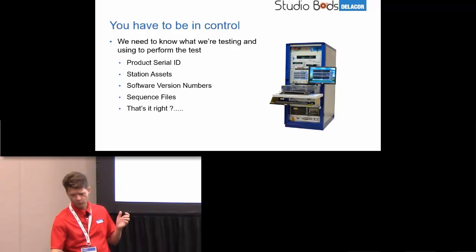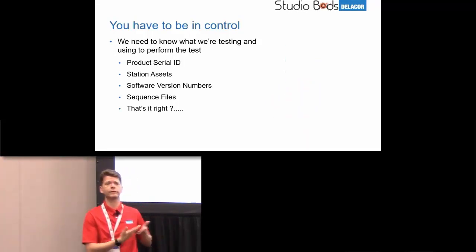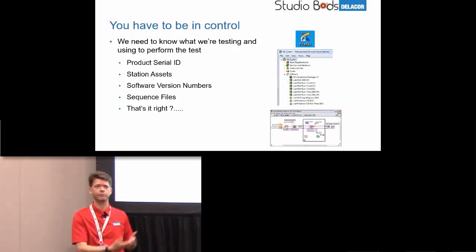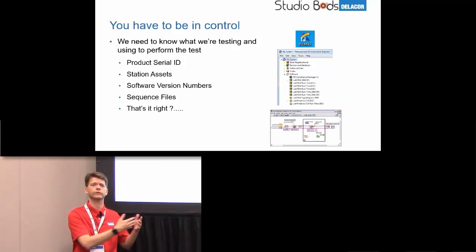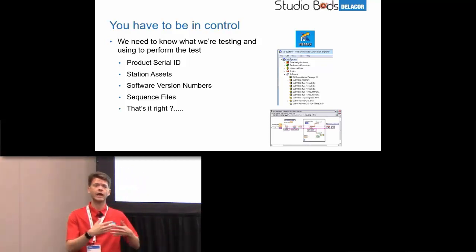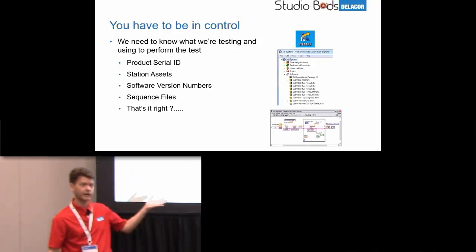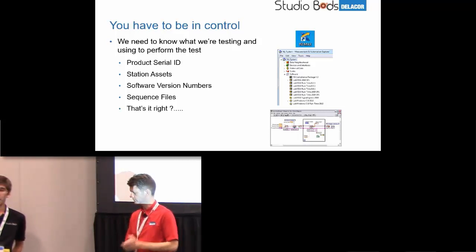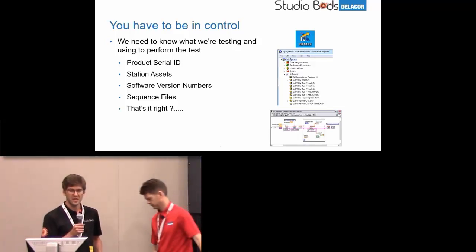Well, no. We need to know things like driver versions. What driver are we using to drive this box instrument? Because maybe it behaves differently. We need to know about National Instruments toolkits that we have installed on our test station. Are they consistent versions? Is there a difference in performance from one version to another? MAX, for example.